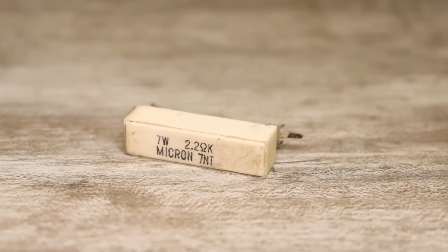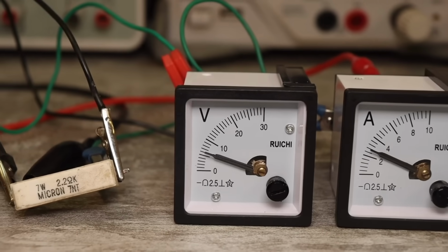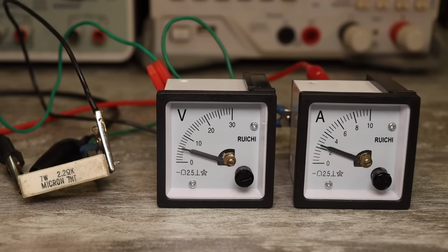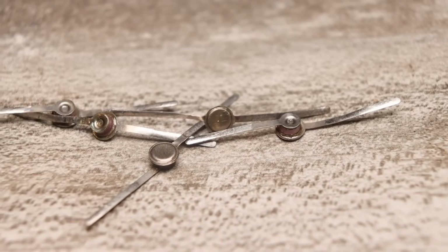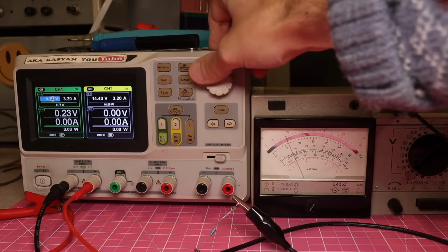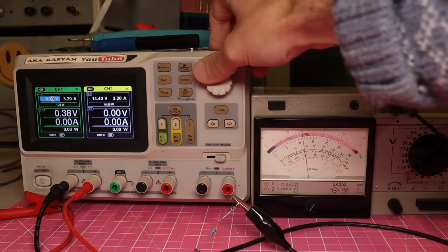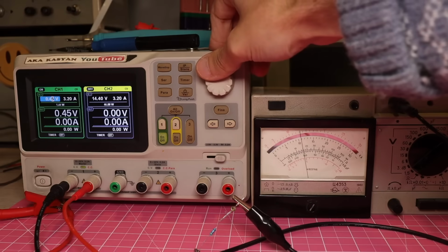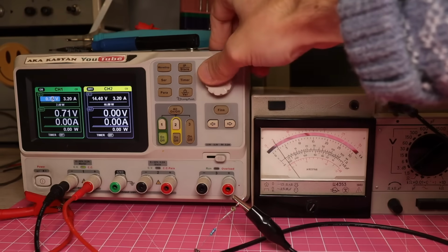We have a load, for example a resistor, and a certain voltage is applied to its terminals. As this voltage increases, the current flowing through it will also increase. This is Ohm's law, but in a tunnel diode, the following happens. If we increase the voltage, the current increases as expected. But when a certain voltage is reached, something strange happens. The current drops sharply, and as the voltage continues to increase, it decreases even more.